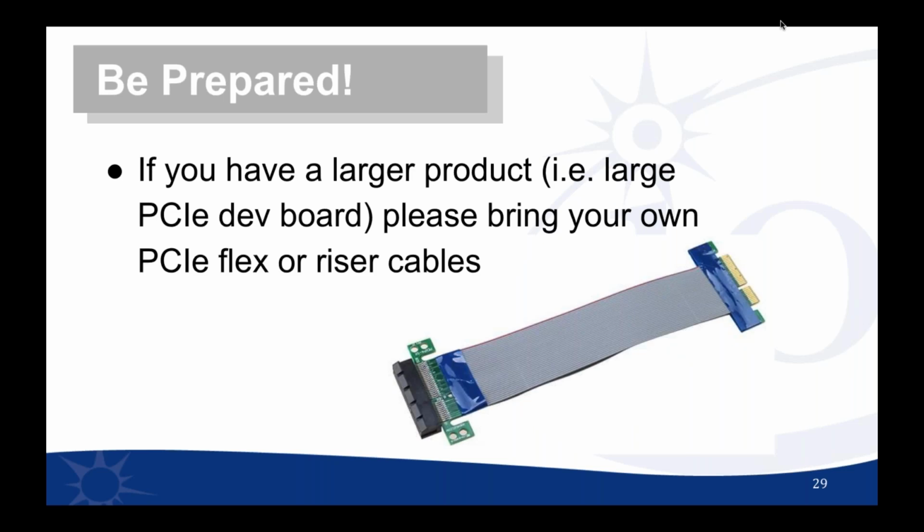Next, if you have a particularly large product, and this is sometimes the case if you're using a PCIe development board, like a large eval kit, sometimes those boards are too big to fit in a PC or server case. If you've got a big product like that, make sure you bring a PCIe Flex or a riser cable so that we can still perform the interop testing.